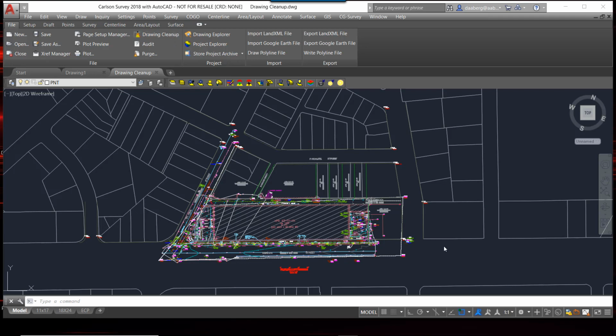If you take a quick look at this CAD file, I can see quickly that the UCS icon here indicates that there is, in fact, a user coordinate system set. User coordinate systems can cause problems with several of the Carlson routines, so those always need to be set to world. Additionally, vertical data errors are one of the most common problems, especially again when it comes to creating a